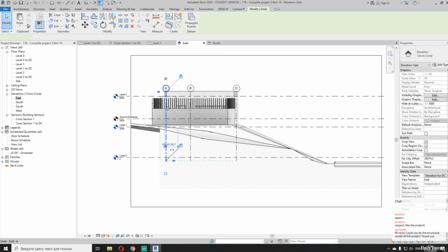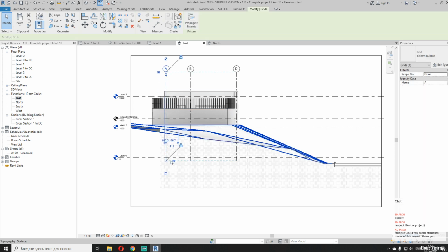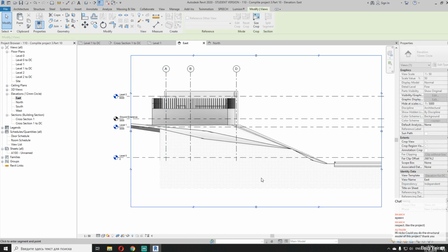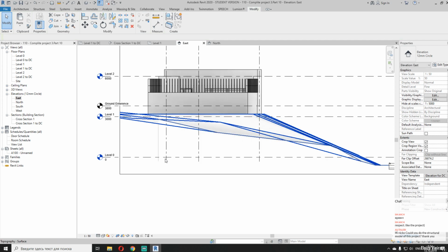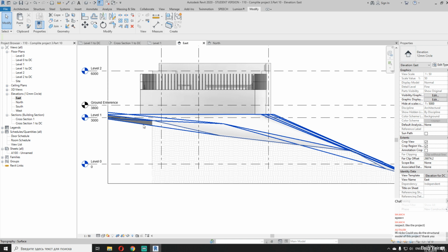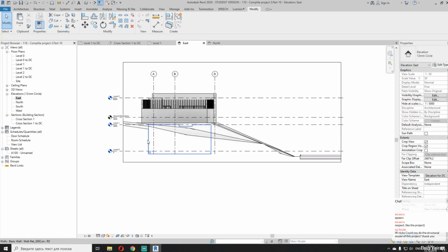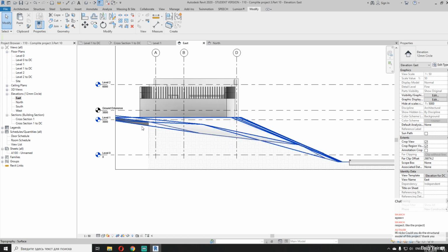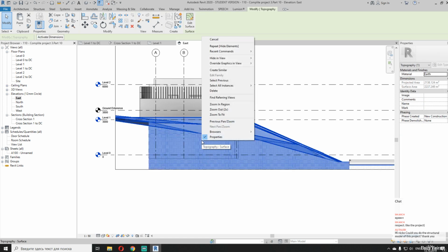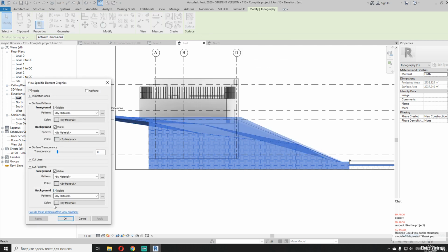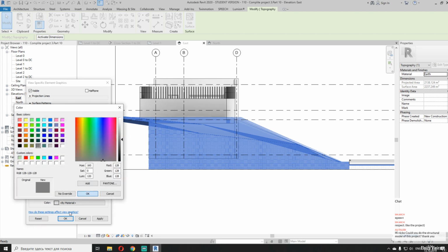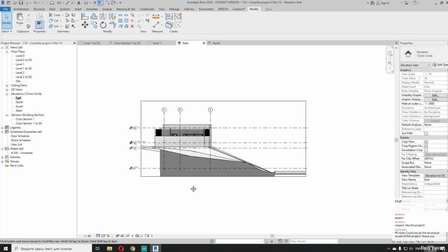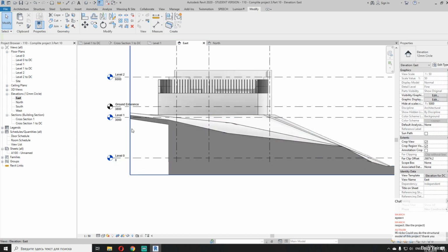And here are my elevations. Let's do it like this. Don't show a lot of your earth. We don't need that. Okay. Let me think. Yeah, we can leave it like that. Just right click on that. Override element. Cut it. Where is my cut? Here. And let's say we want to use this color. Okay. Nice. We have a problem here, because the problem is only about the 3D.